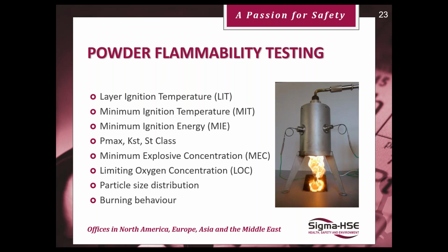The steeper that is, the more violent the explosion is. And we need to use this sort of data for determining the size of our vents and how quickly our vents need to open, and so on and so forth.